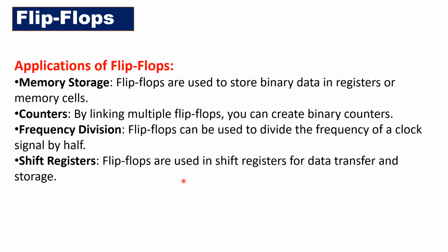A sequence of flip-flops can form a shift register which transfers data from one flip-flop to the next with each clock pulse. This allows for serial to parallel or parallel to serial data conversion and is fundamental in data processing and communication systems like UARTs or SPI.